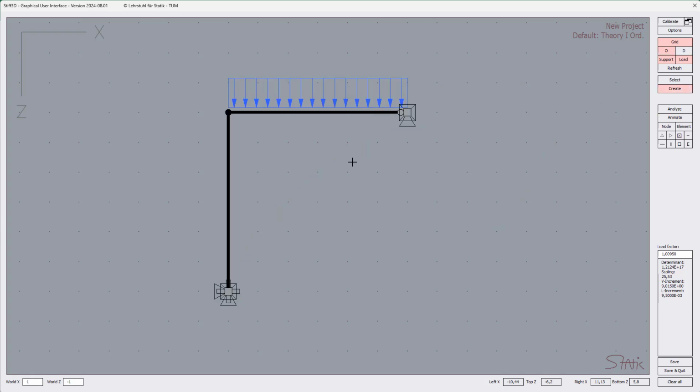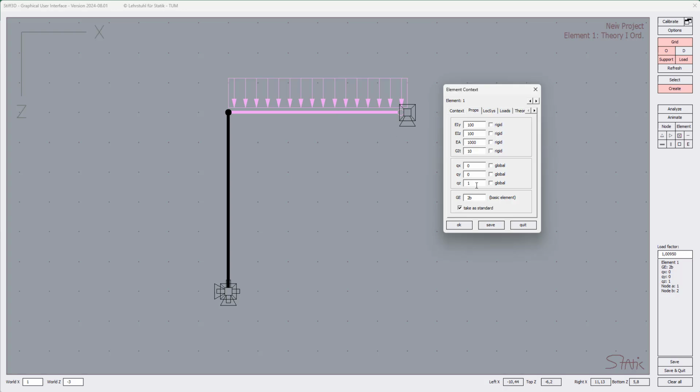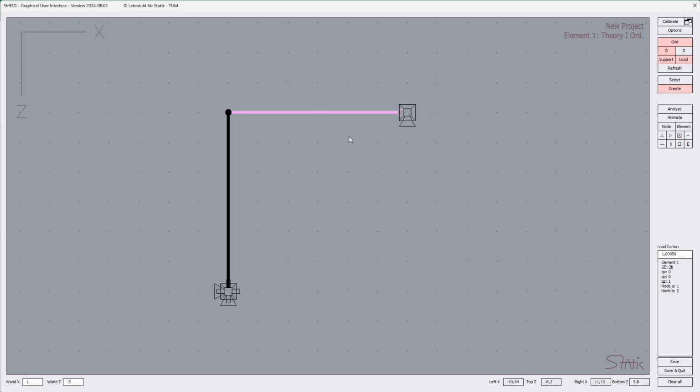So far so nice. I would like now to look at a different kind of loading. We take away this line load, and I would like now to load this beam just in the center by a single load. How can we do that? We can do that just by introducing another node here, and you see for that we need this split option for the element.